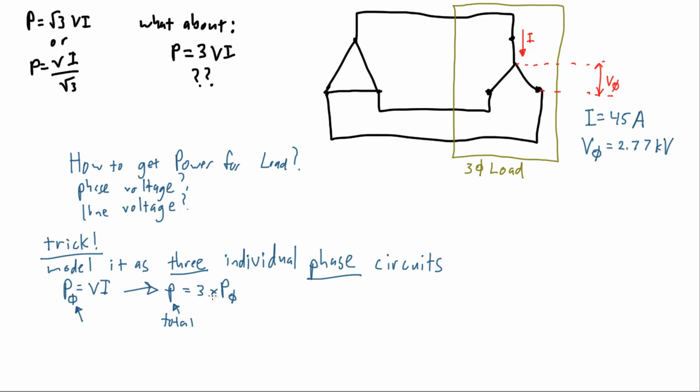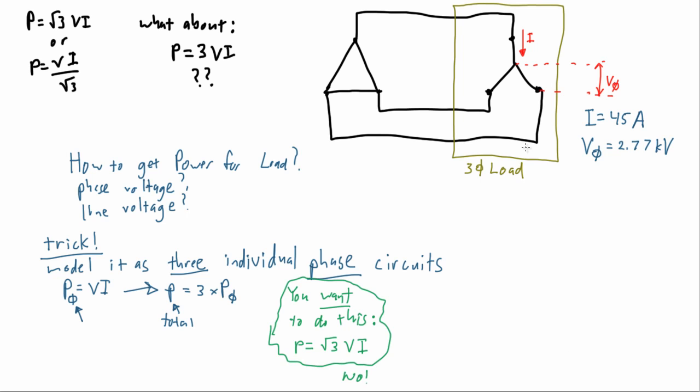And this is the point that a lot of engineers are going to get confused because they're going to be so ready to use that root 3. They're thinking polyphase loads, this seems like a situation that is familiar for the root 3 to be applied, and so they're going to want to whip the root 3 out in their calculations inappropriately in a situation like this one.